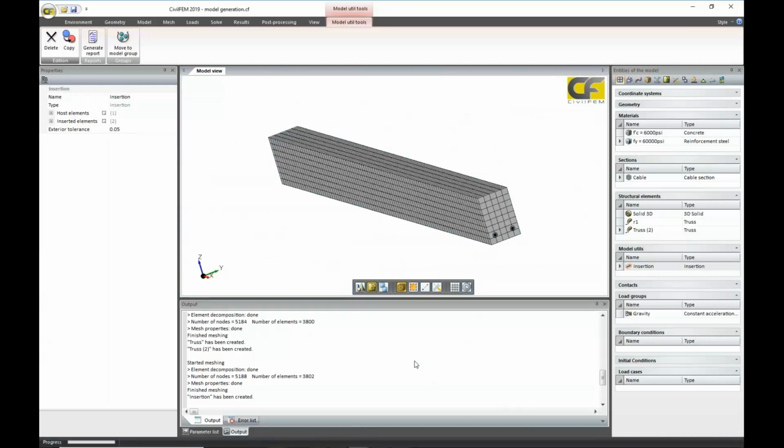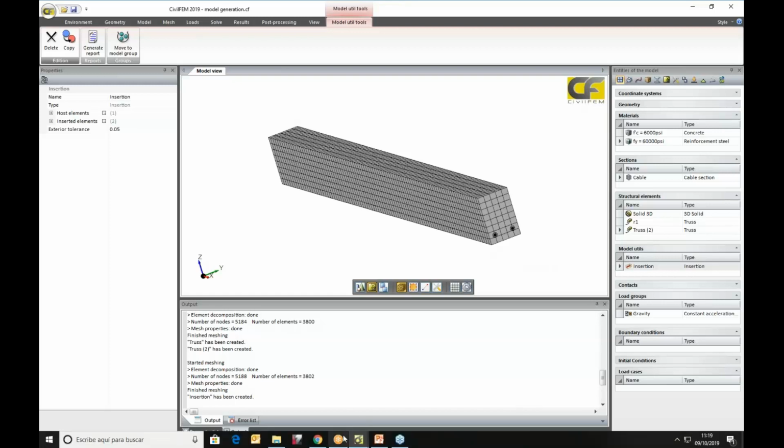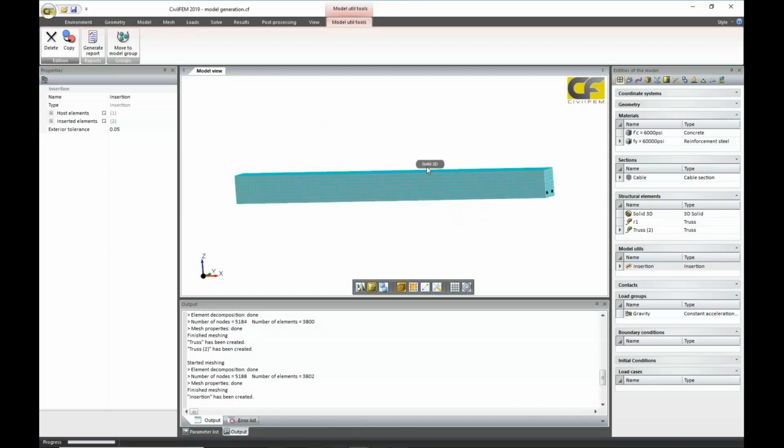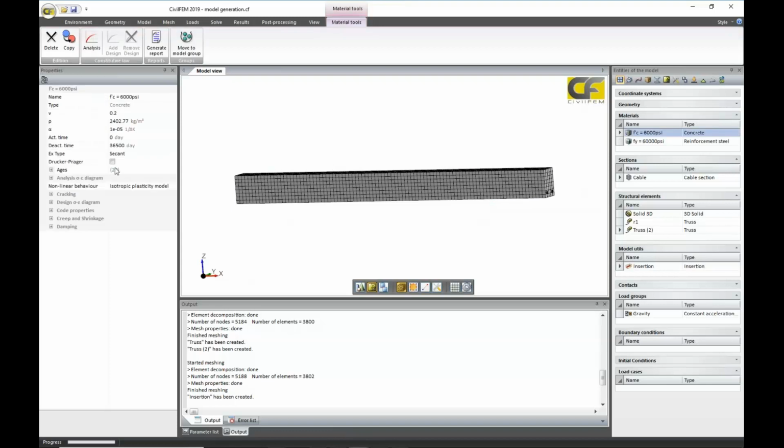So well, I did all the examples following these options, but I modify the bending reinforcement diameter and the different reinforcement configuration, and apply a load, 2 loads on top at a distance of half a meter from the support. It has 1.5 meters span length, and I apply loads with different reinforcement configuration and analyze the possible failure. You will see them in the slides now.